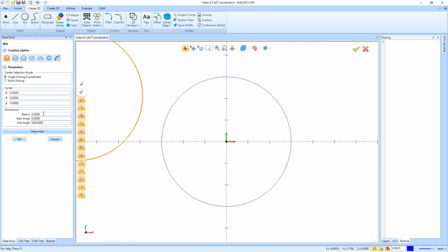So now I'm going to change the size of this to 0.1875, 3/16. And then I'm going to go ahead and take my X and set it to -2.5. And then just click in another box or again hit Tab, and then I'm going to hit OK. And then I'll go ahead and make another one that goes to X 2.5. And now we have 2 holes on both sides. So we'll go ahead and hit OK there.